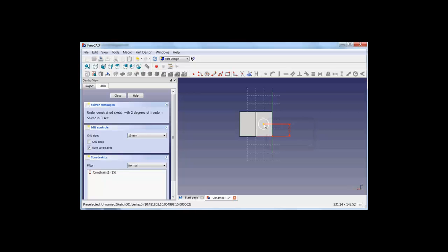Now, for example, I want to define the center of my circle to this line. And this line is not known yet in my sketch. Of course, FreeCAD knows that this line is here, but I cannot dimension from this line. So I have to get this line into the sketch of my circle. And I do this with this tool, create an edge linked to an external geometry. And then I click on this line, and then you see a kind of purple, pink, magenta line.